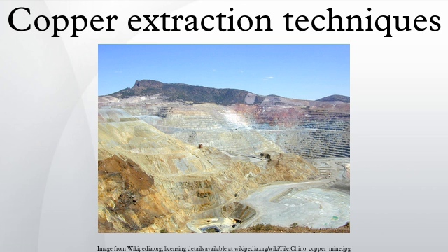For oxide ores, a hydrometallurgical liberation process is normally undertaken, which uses the soluble nature of the ore minerals to the advantage of the metallurgical treatment plant. For sulfide ores, both secondary and primary, froth flotation is used to physically separate ore from gangue. For special native copper-bearing ore bodies or sections of ore bodies rich in supergene native copper, this mineral can be recovered by a simple gravity circuit.